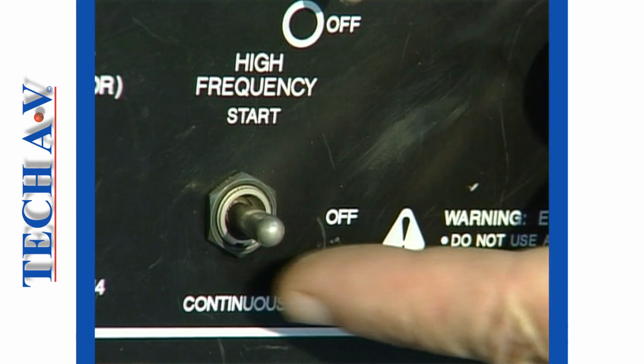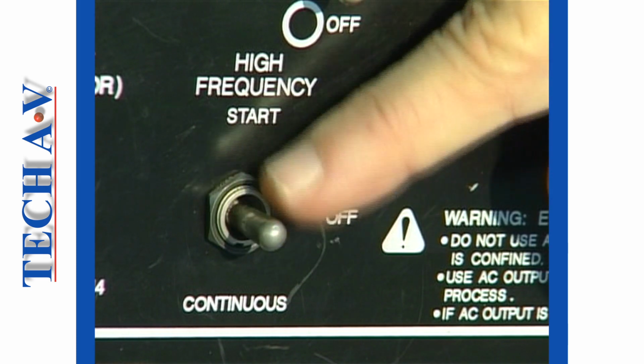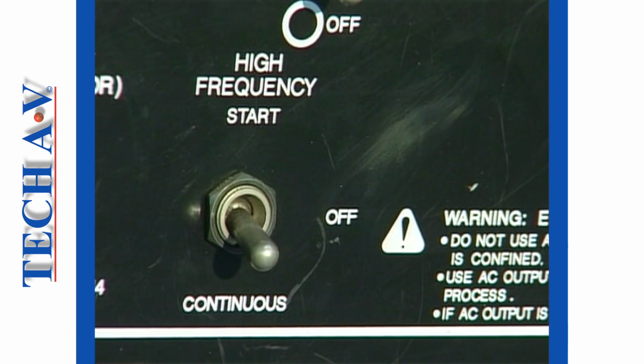In the up or start position, the HF voltage acts only when the welding current starts. That is, when an arc is struck. This mode is used when DC current is selected. In the down or continuous position, there will be HF at the electrode continuously, whilst the current is set to AC.